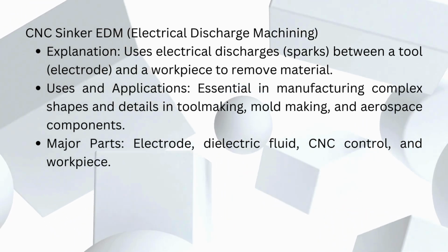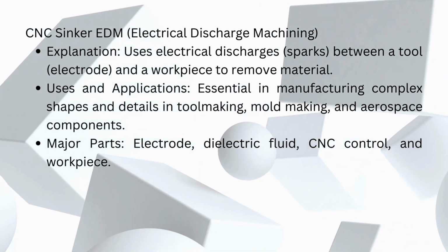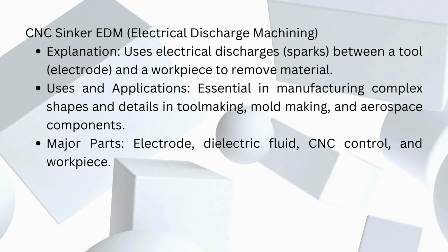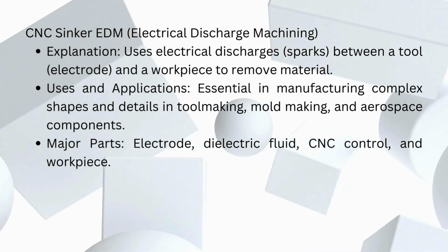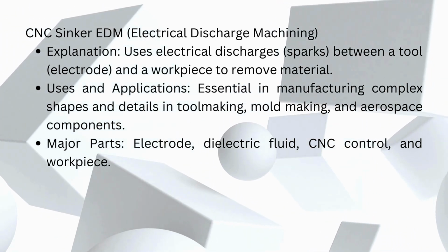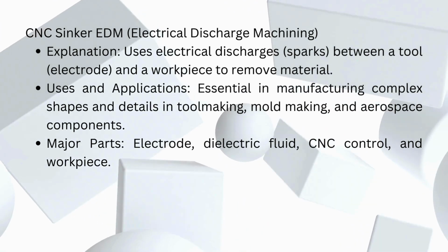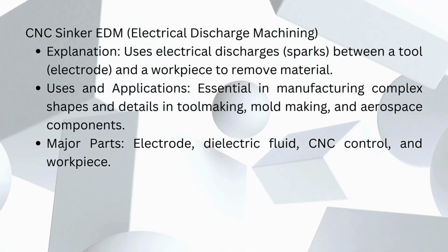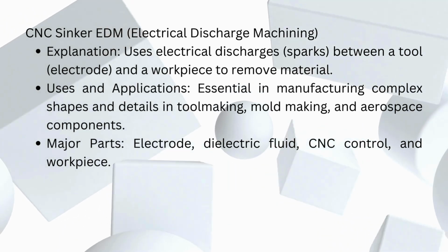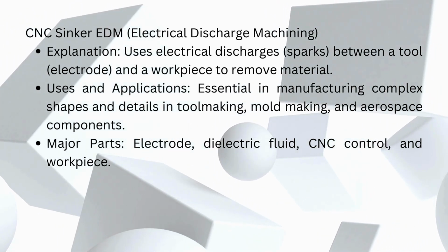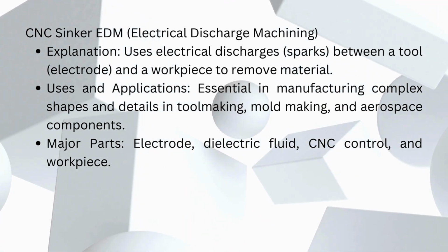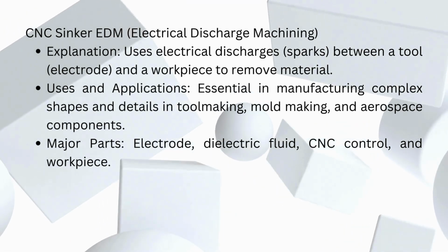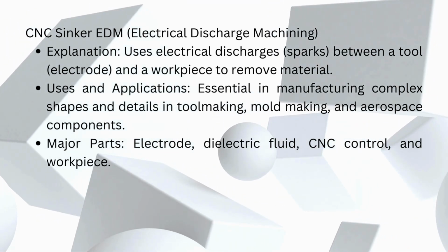CNC sinker EDM, electrical discharge machining. Explanation: uses electrical discharges, sparks, between a tool, electrode, and a workpiece to remove material. Uses and applications: essential in manufacturing complex shapes and details in tool making, mold making, and aerospace components. Major parts: electrode, dielectric fluid, CNC control, and workpiece.